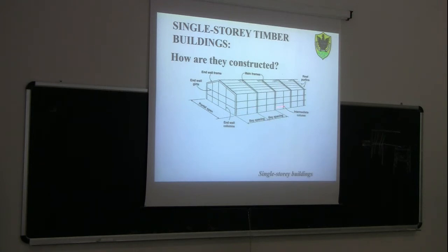However, if you design a lightweight structure, a structure like this made of either steel or timber, try to use also lightweight cladding, because otherwise, as you know, when you do the seismic verification, a structure which is very lightweight with some very heavy cladding doesn't work well. Heavy cladding means that it also transmits quite significant seismic forces on the building itself.